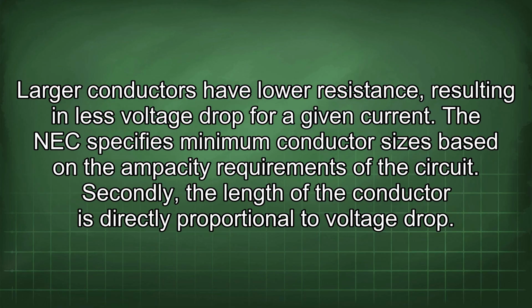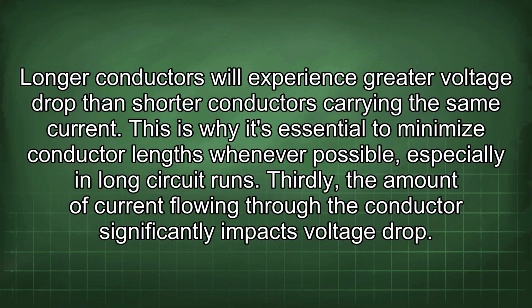Secondly, the length of the conductor is directly proportional to voltage drop. Longer conductors will experience greater voltage drop than shorter conductors carrying the same current. This is why it's essential to minimize conductor lengths whenever possible, especially in long circuit runs.